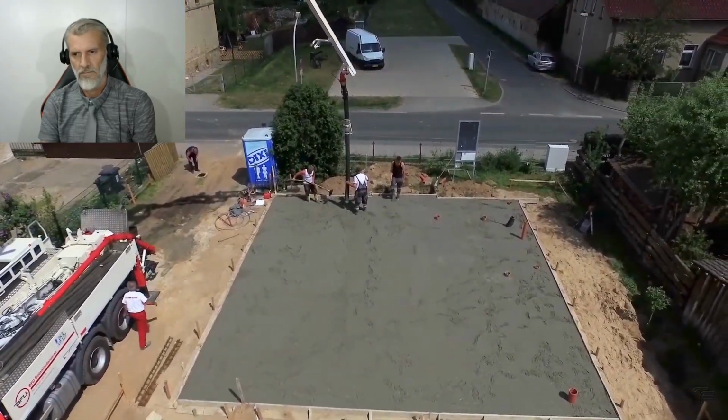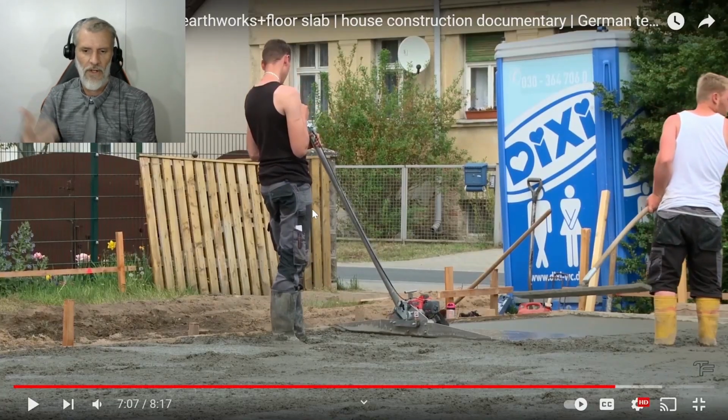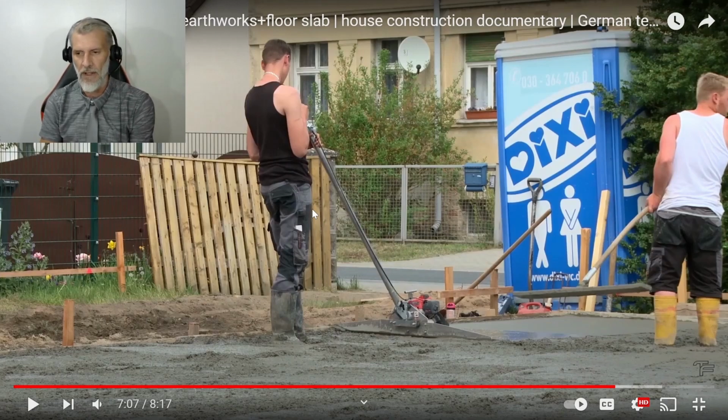Done. Now the concrete has to be compacted. They're doing the same thing here. They're screeding, compacting and vibrating at the same time. You can see the bubbles coming up through the concrete. It's exactly the same principle. You've got to get the air out of the concrete so that it's solid. That machine, whatever it is, would do exactly that. I actually like that because it's screeding at the same time.